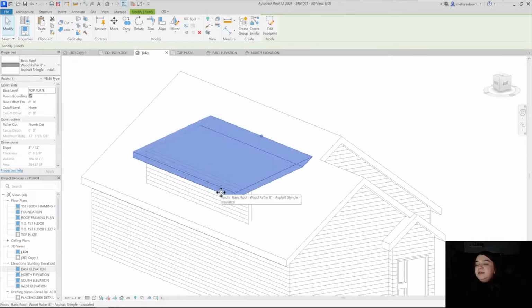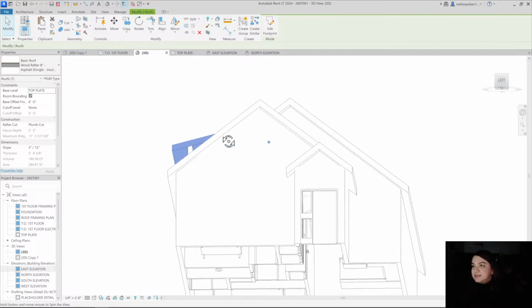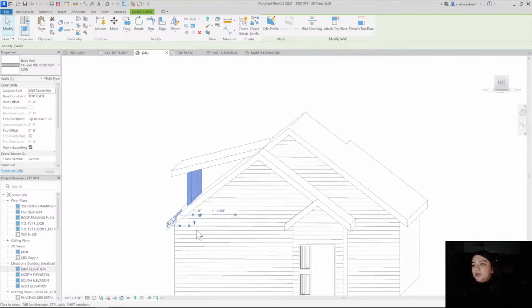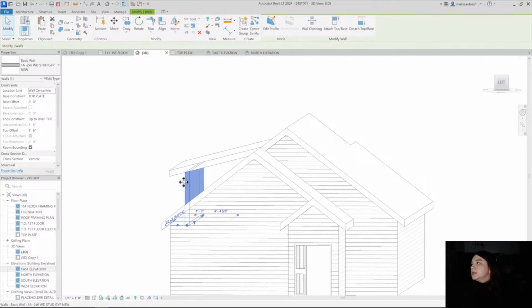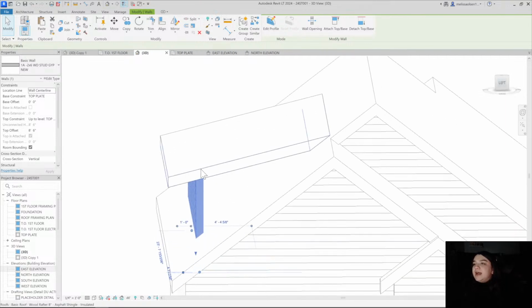Sometimes having different push and pulls on the facade really makes it feel more intentional, like you didn't just copy and paste the wall up. You thought about the proportion of the space and what you wanted to do with it. But like I said, if your customer is trying to max out that space, they're probably going to want you to not waste square footage and just move the wall back out to align with below.